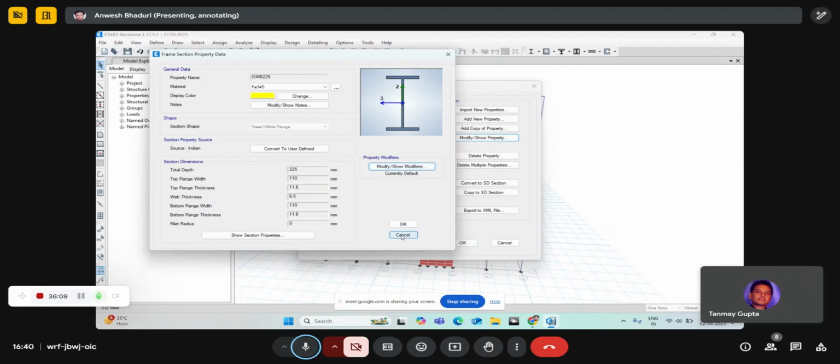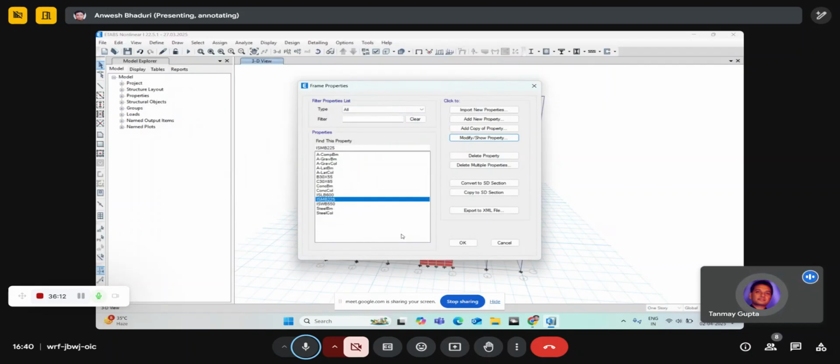Is there a provision for connection here? What is it considering for the connection between two steel members, a welded one? If you just model it, it will take it up as a rigid connection. For the moment releases, we need to apply them externally. Whatever moment releases are there need to be defined externally. If it's a semi-rigid connection, you can find out from the M-theta curve, whatever the type of connection is, and some partial fixity can be given.